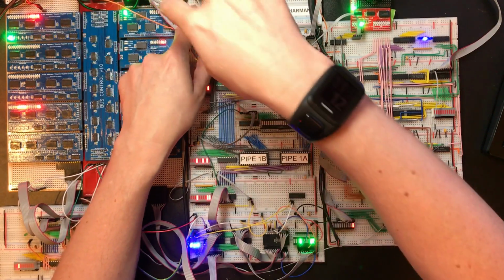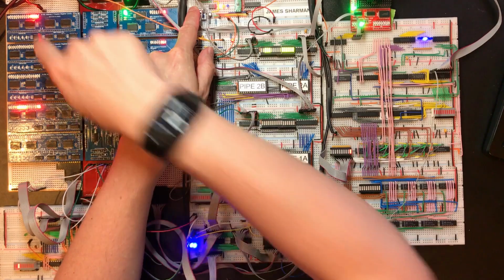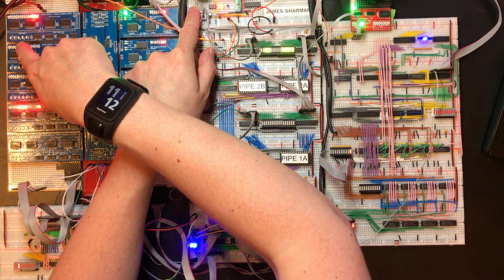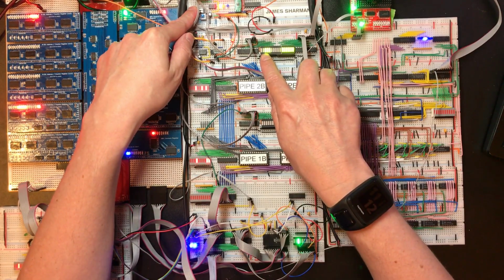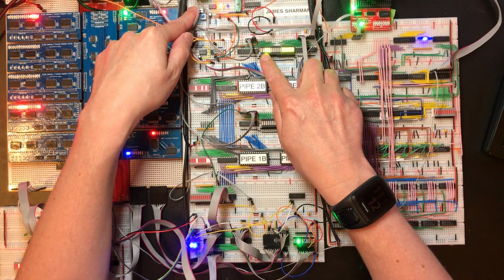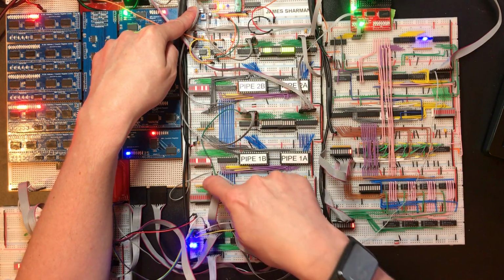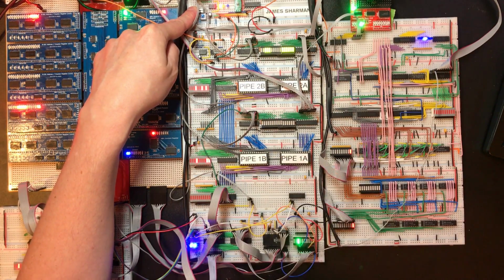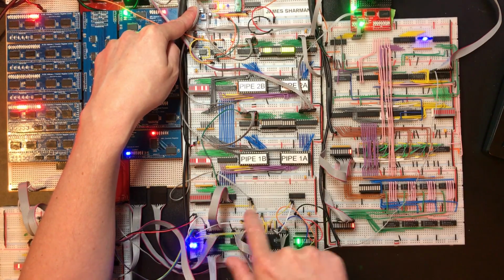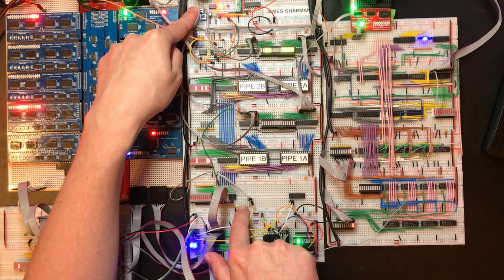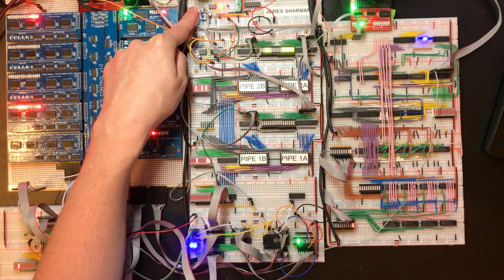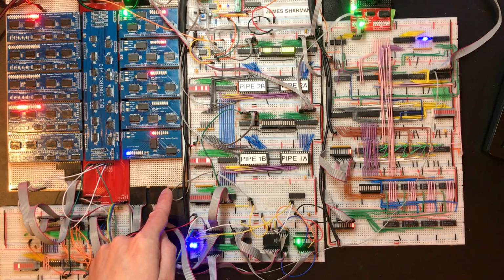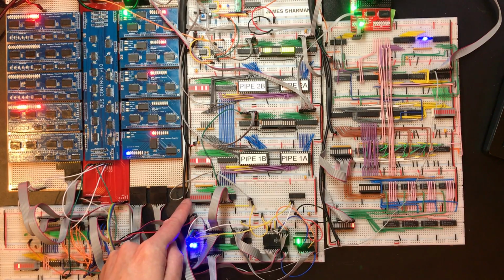Watch the program counter. This incremented, but we didn't see the increment light come on. And we didn't see that because the bus request line is set, which comes all the way down here, which causes the fetch to emit a NOP, but it also sets this line high, which is what's supposed to stop the program counter from incrementing. So that is where we've skipped over the load from the address of TX.